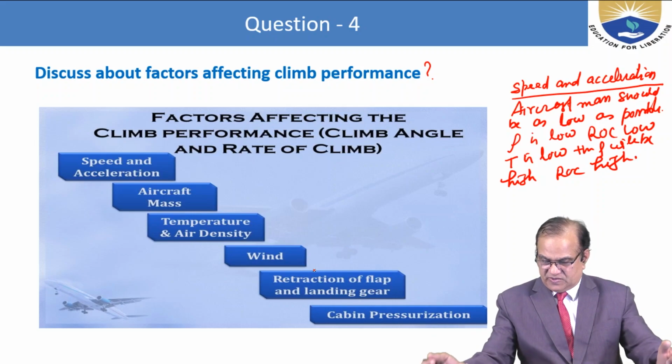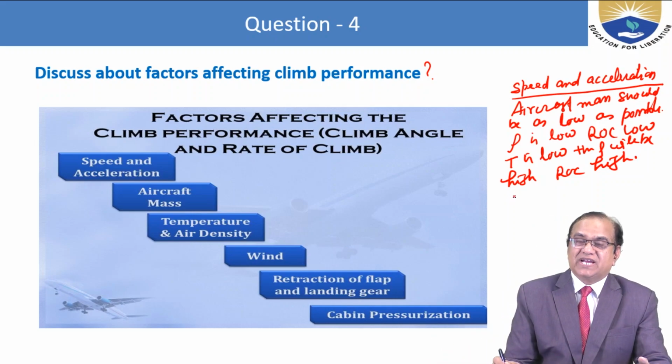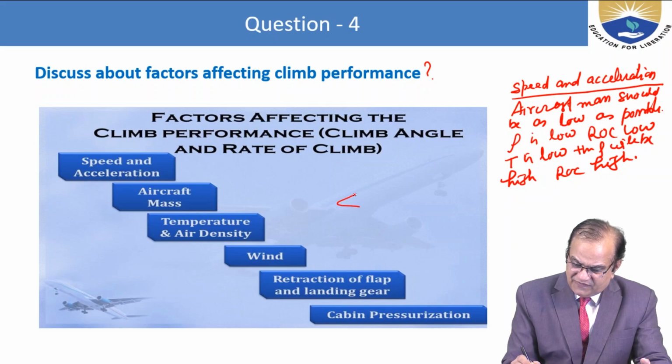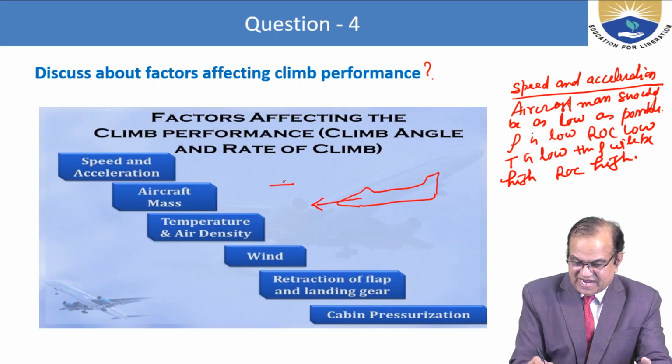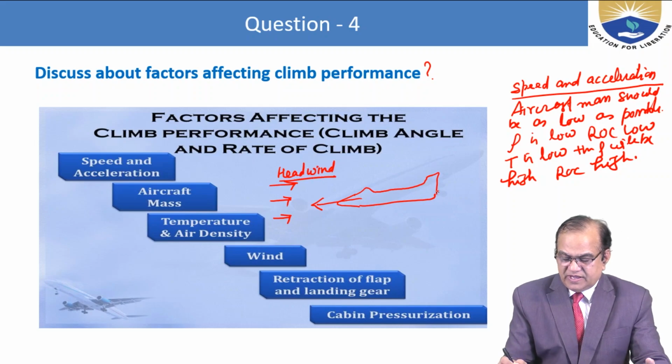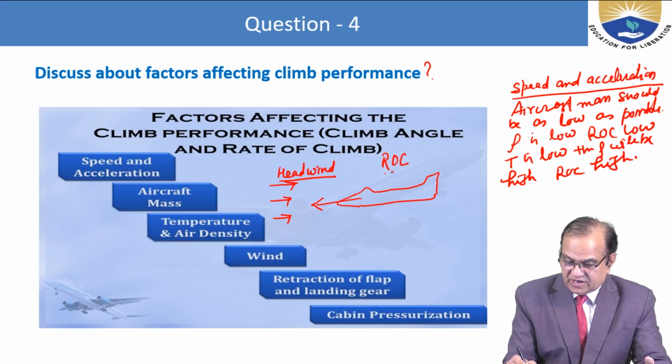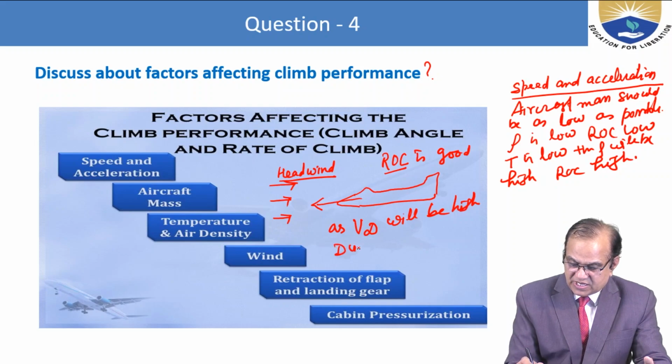Next is wind. This also depends upon the wind condition. So if it is a tailwind or the headwind, aircraft is moving in this direction, and if this is the headwind, in headwind the ROC is good, rate of climb is good, as V infinity will be high during headwind.